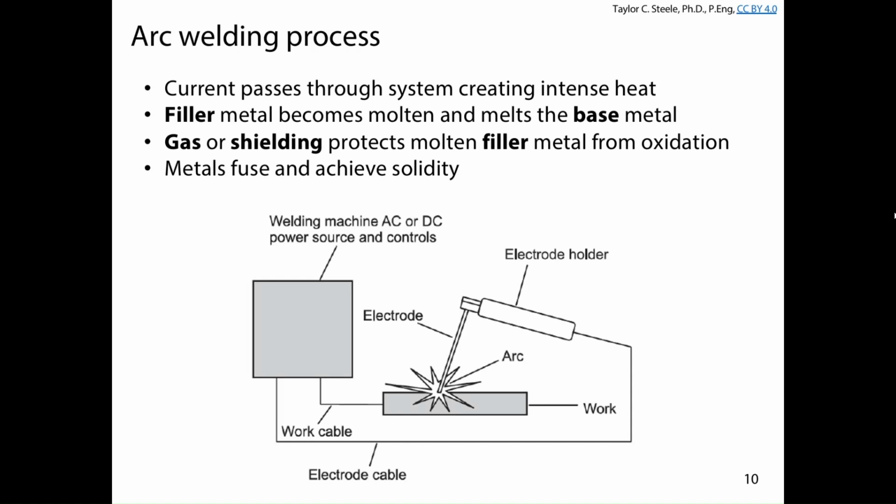You can do arc welding a bunch of different ways. You can use gas shielding, or a shielding to protect the molten filler. That electrode protective coating is called flux. When you weld, that flux falls off and protects the molten metal. Steel, when molten, can corrode very quickly, so once it's molten, you need to protect it from corroding.